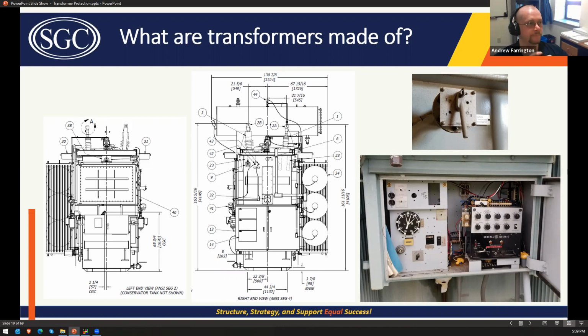Yep. Oh, okay, thanks. If I could just add too, it's for the cases where the load varies quite a bit over the course of a day. So you tend to see way more load tap changing transformers on distribution circuits because the load varies so much. It would be almost impossible to maintain the nominal voltage under low load or high load conditions. So it operates a fair amount, mainly on distribution circuits.